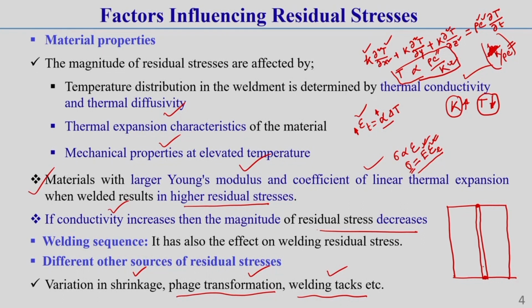Why is this gap provided? Because not to provide short circuiting phenomenon, and to fill this gap by providing this filler material properly. That is why this gap is provided. To make this gap properly, it is required to provide some small weld deposition. So these are called tack welds, because this tack weld is required to align the workpiece properly, so that this gap remains maintained.